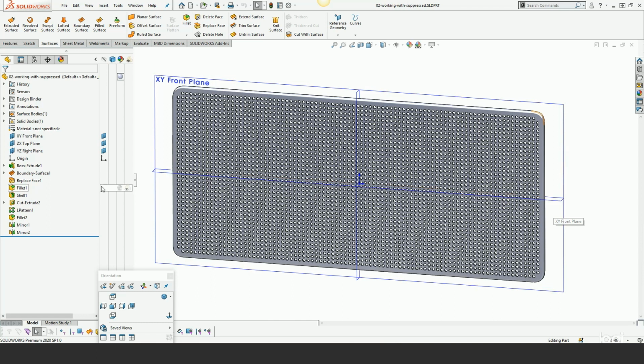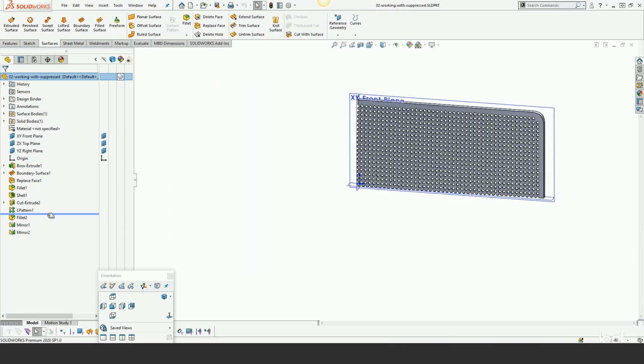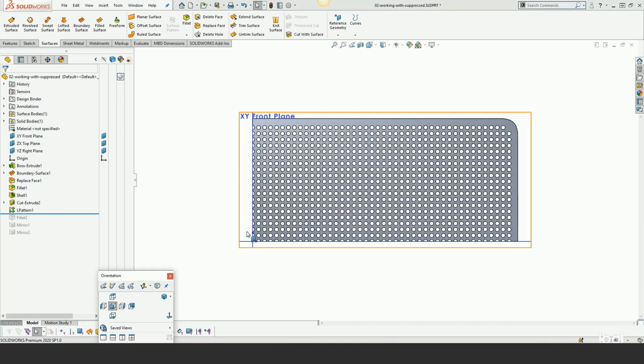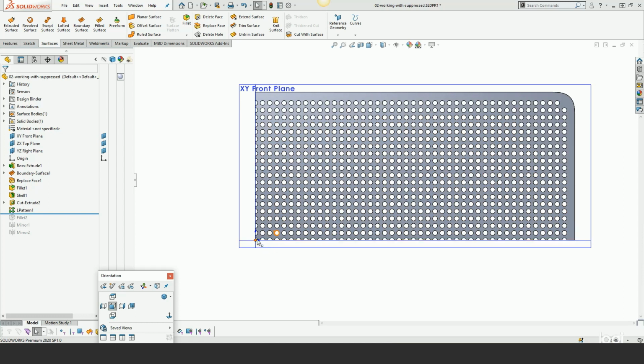So let's roll back to this pattern, and you can see that I'm building 1/4 of the model and 1/4 of the pattern, and then mirroring it by 4. That increases the speed if you're not aware of that. If you can model that way, it's a good way to do it, and it's more robust. Here the designer wants to change these holes to a smaller hole, resulting in a smaller spacing and more holes.